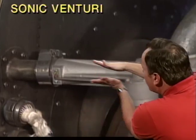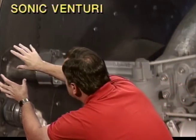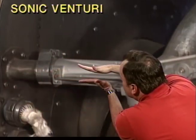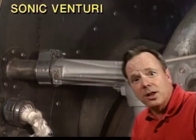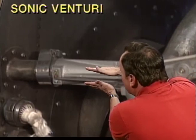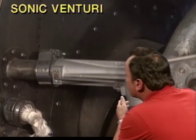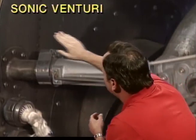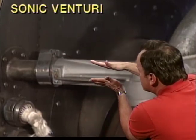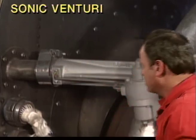It's a narrow part in the outlet from the turbocharger to the pressurized cabin, forcing the air to go through that narrow part. Bernoulli's law says it's going to speed up as it goes through that venturi, and it will reach the speed of sound. And the speed of sound limits the rate at which air will travel through this venturi. It's called a sonic venturi, and once the air reaches the speed of sound, it will not go any faster unless certain other conditions exist, which we don't have here.